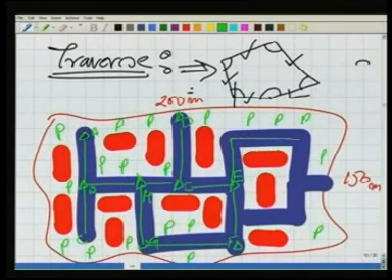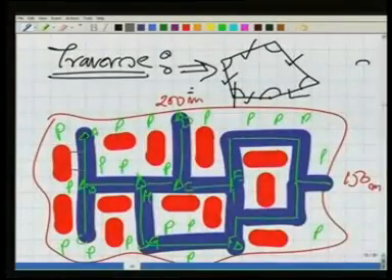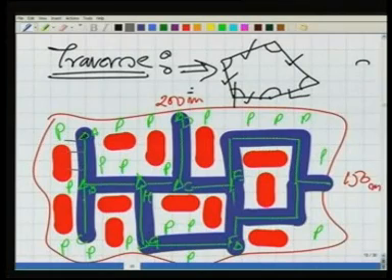Well, we can keep going like this and we can cover the entire area. But will it solve our purpose? Well, I can take the offsets for these buildings, this tree from the line here. I can also take the offsets to these buildings from these survey lines.